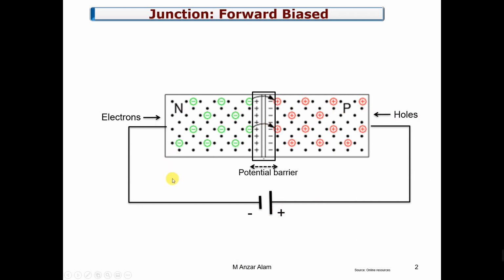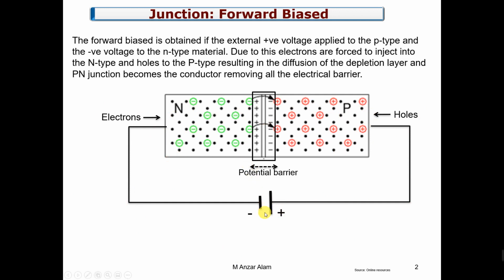So the point is that at 0.1 volt, there will be a potential barrier with a reduction in its thin layer. So there will be less flow of current. And as we increase the supply from 0.1 to 0.2, 0.3, there will be more flow of current. But when we break this barrier completely, and we can break this barrier completely at 0.7 volt or at higher volt, there will be inrush current, there will be maximum flow of current.